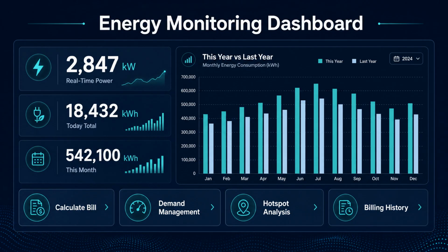Our platform leverages advanced artificial intelligence models, including XGBoost and Prophet, to analyze equipment data every 15 minutes. The system generates actionable optimization recommendations, complete with confidence levels and estimated savings. For example, it might suggest raising a chiller set point from 6 degrees to 7 degrees Celsius during peak hours to save 8% in energy, with a confidence level of 91%. You can choose to accept these recommendations for automatic execution via the gateway or perform them manually. The system will track the savings over a 7-day verification period.